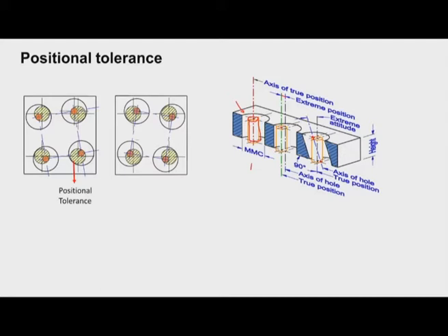If it is within the allowed deviation, then we can accept the workpiece. This is the true position, and this is the extreme attitude, the axis of the actual hole that is drilled.